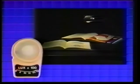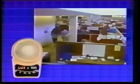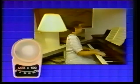With a light meter, you can easily measure the illuminance of any area. The average office is between 500 and 1,000 lux. That's 50 to 100 foot candles. Remember, the light illuminating any area is affected by the lighting fixture, too. The same lamp will give you different results with different fixtures.